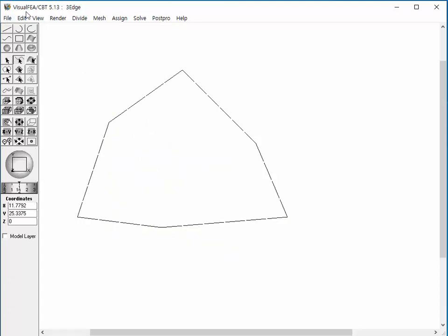The next example will show how to combine multiple curves for each of the boundary lines. In this example, 6 straight lines are given with divisions, as indicated on the screen. They must be combined to form the 3 boundary lines, compatible for mesh generation. 2 alternative combinations are possible in this case. One combination is obtained by pairing 2 adjacent curves as indicated. The alternative combination is obtained by pairing curves differently. For either case, each boundary line has 10 segments.